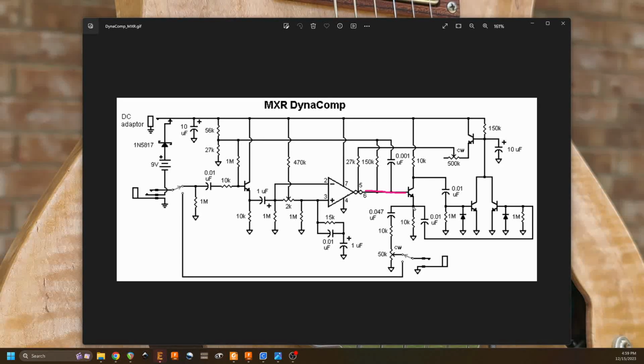It gets split. This is often called a phase splitter because it's equal magnitude and opposite phase. In fact, if we were to swap this out for a tube, that would be exactly what tube amps do prior to sending the signal to a push-pull pair of tubes in an amplifier. And then we have two identical pieces of circuitry.